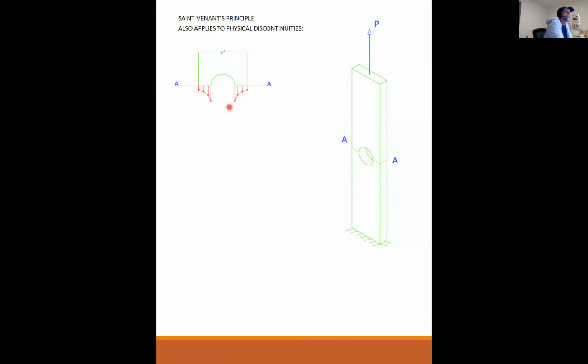They're called stress risers. Whenever you have a discontinuity, you create a non-uniform stress like so. At the hole, the stress is highly disrupted. If we move down a bit to cut BB, right at the bottom of that hole, you still have this discontinuity of stresses. And right at the bottom of the hole, there actually is no material there, so the stress has to equal 0 at that point. But the same principle applies.